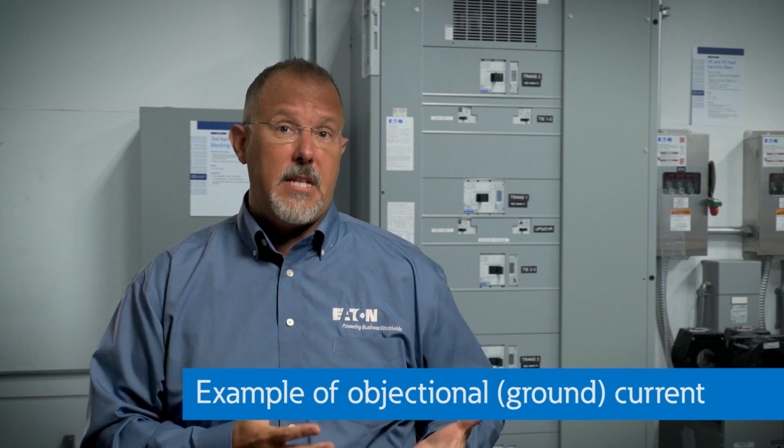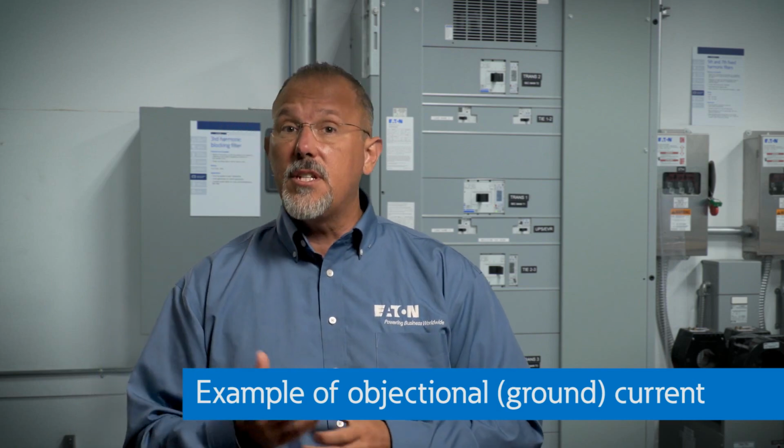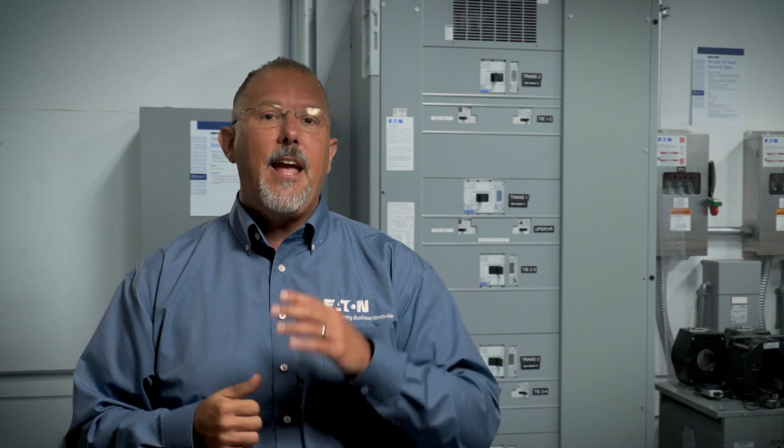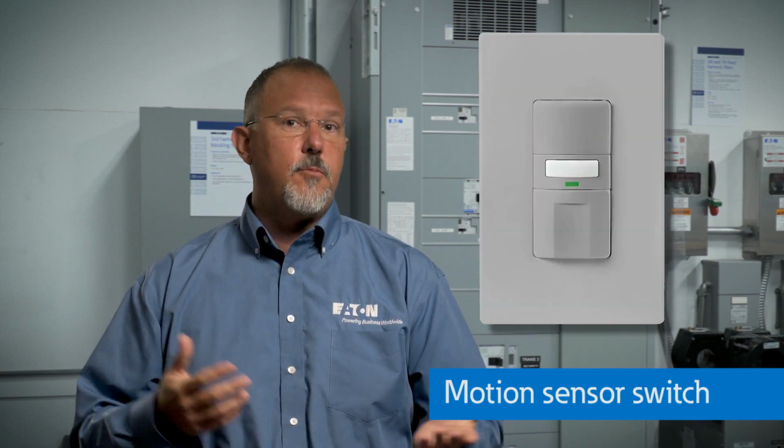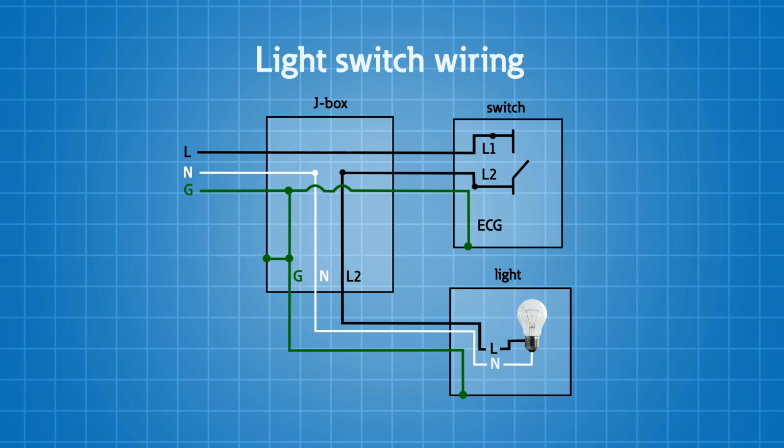And I think to best understand this, let's just talk about an example that you are probably well aware of because it received a lot of attention over at least the last 2 cycles in the National Electrical Code. And these are those motion sensor type switches that you'll find in either residential homes or commercial buildings, where you walk into a room and it turns the light on. If you think about how we wired residential homes or any types of structures when we came down to a light switch, what did we do? We brought one set of conductors, and that was our hot conductor. And we brought an equipment grounding conductor as well. And we did not bring a neutral.